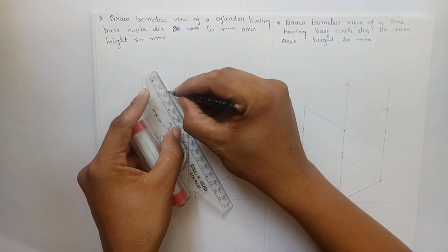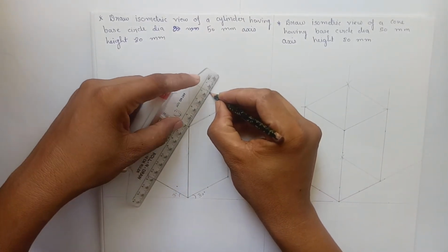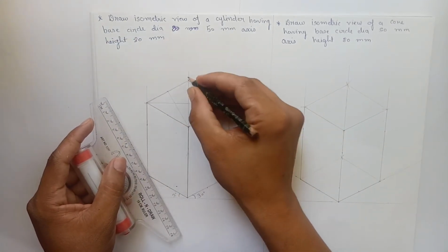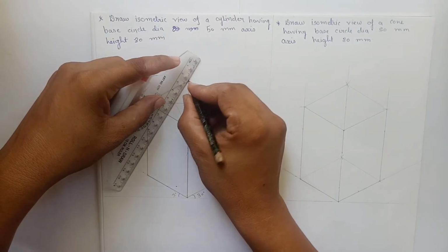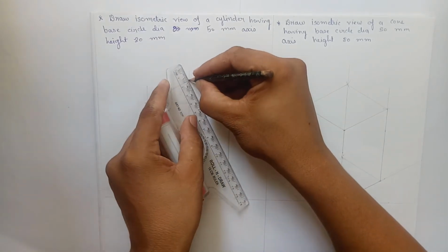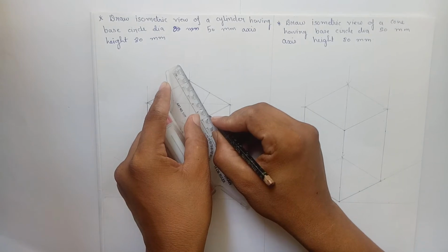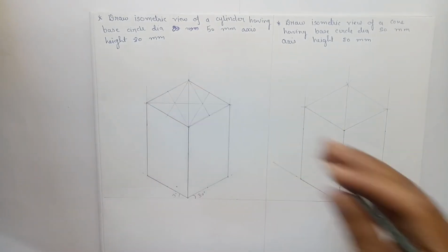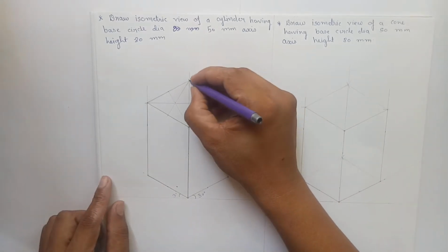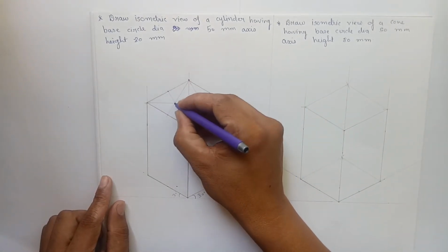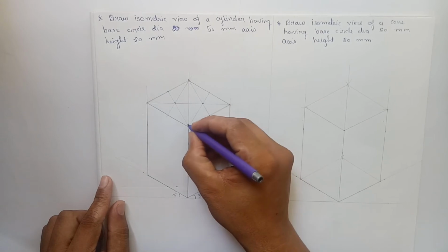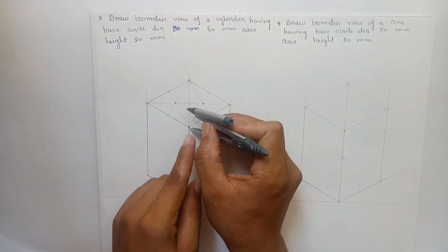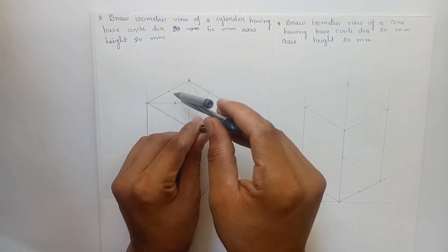Connect this point to this midpoint to this corner to define another two centers, as we have to draw this circle by using the 4 center method, and it will be an ellipse by the 4 center method. So now we have 4 centers, 1, 2, 3 and 4.